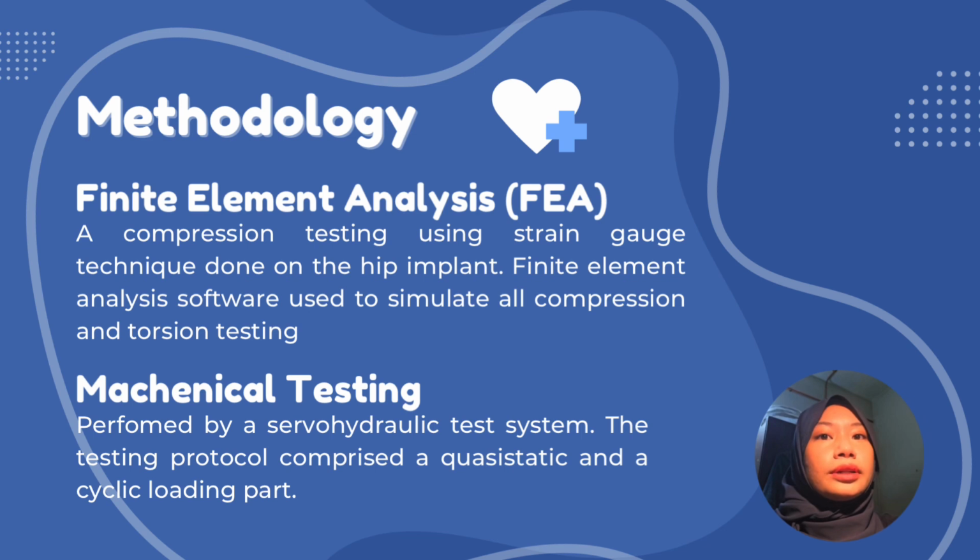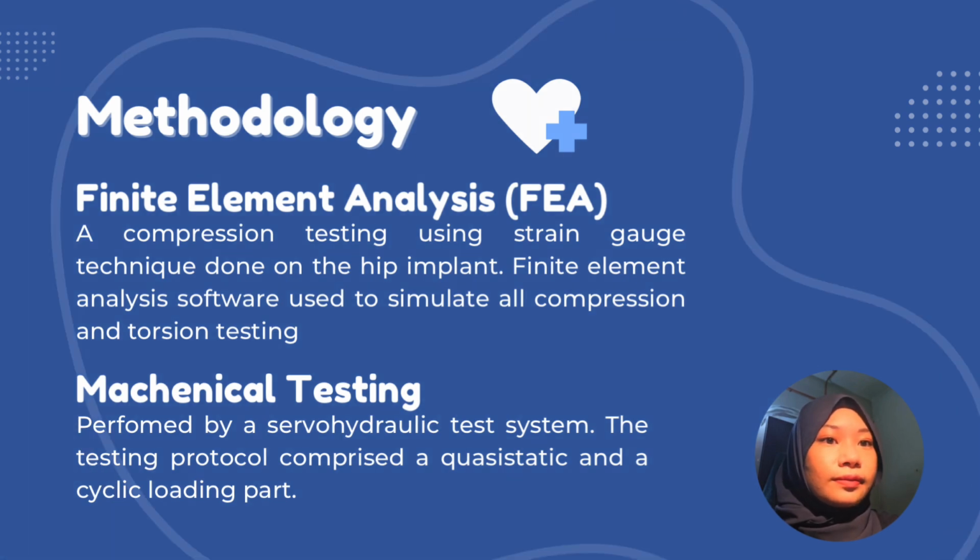Based on the load displacement curve, axial construct stiffness, failure load, and cycles to failure will be defined as parameters of interest for each specimen and considered for statistical evaluation. Axial stiffness was calculated from the gradient of the respective load displacement curve during the ram loading in the quasi-linear elastic region before the plastic construct deformation occurred, and failure load, cycles to failure, and type of failure were defined from the destructive cyclic test itself.